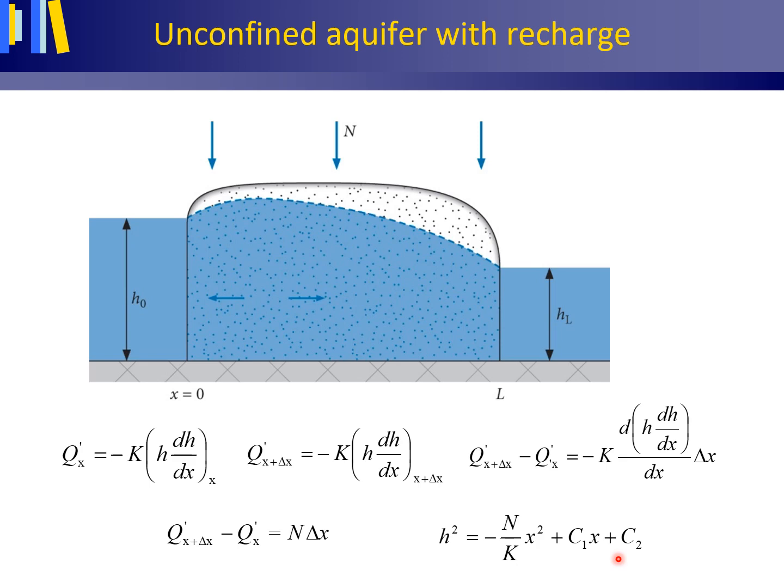Note that as this flow case is not symmetrical, the location of axis 0 is now taken to the left. And we find values of C1 and C2 by inserting the boundary conditions as explained earlier. First insert the left boundary condition and then the right one, etc. Also remember that from work by Haitjema and others, as mentioned in an earlier lecture, a low average annual recharge rate in comparison with the aquifer's transmissivity is favorable for the establishment of such a recharge-controlled water table.